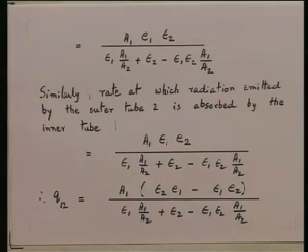That is the net heat exchange rate between the two surfaces. All right. We are proceeding exactly in the same way that we did for infinite parallel plates, with the difference that the shape factor in one direction is 1, F1 to 2 is 1, and F2 to 1 is A1 upon A2. That is the only difference in this case.